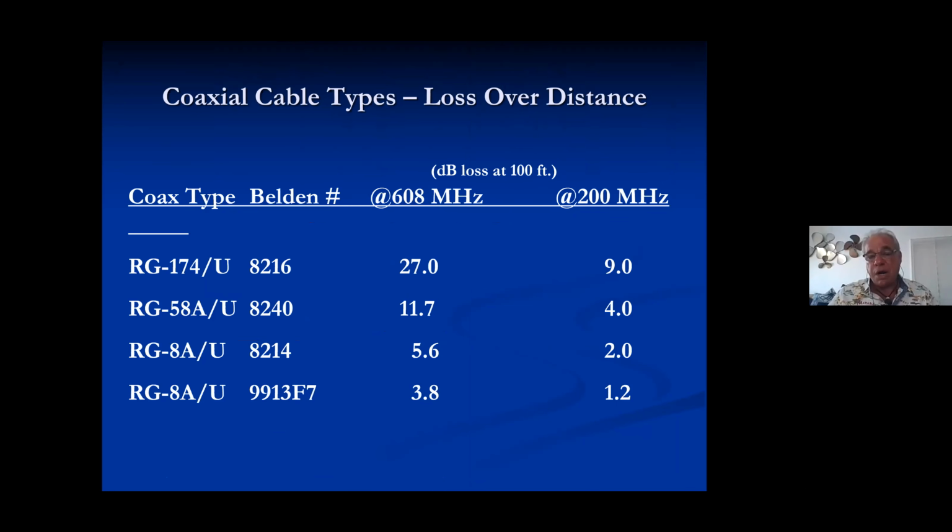But as you go up higher in frequency, where the top end of the legal limit is, we'll get into that more next month, but we have over 3 times the loss at those frequencies. So I generally try not to run more than 100 feet of cable. If I do, I'm definitely using a gain antenna. And if it's more than 100, well, I try not to run more than 150 feet. If you do, now you're implementing RF amplifiers and things of that nature.